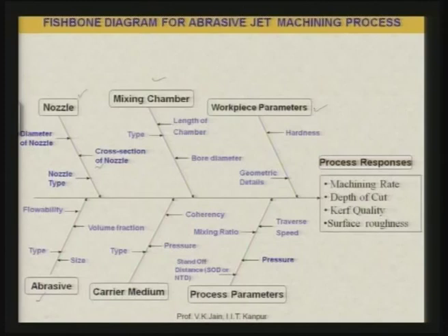Abrasive, if you see flowability of the abrasive, type of the abrasive, I have shown you various types of the abrasive, size of the abrasive again a very important parameter, and volume fraction of the abrasive which is flowing along the air abrasive jet, that is again a controlling parameter as long as material removal rate is concerned. Also it controls the accuracy of the machined cavity.